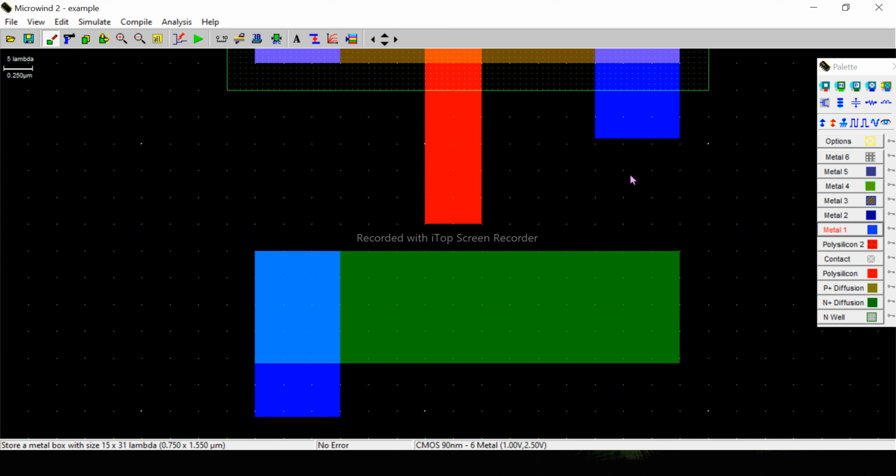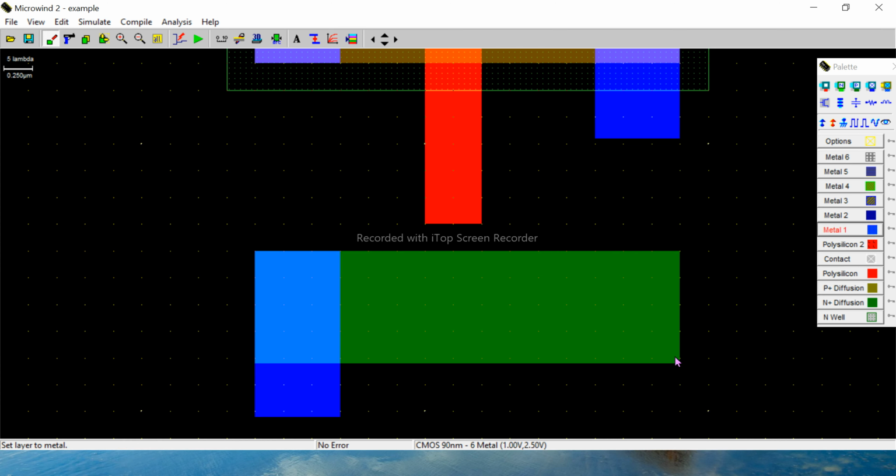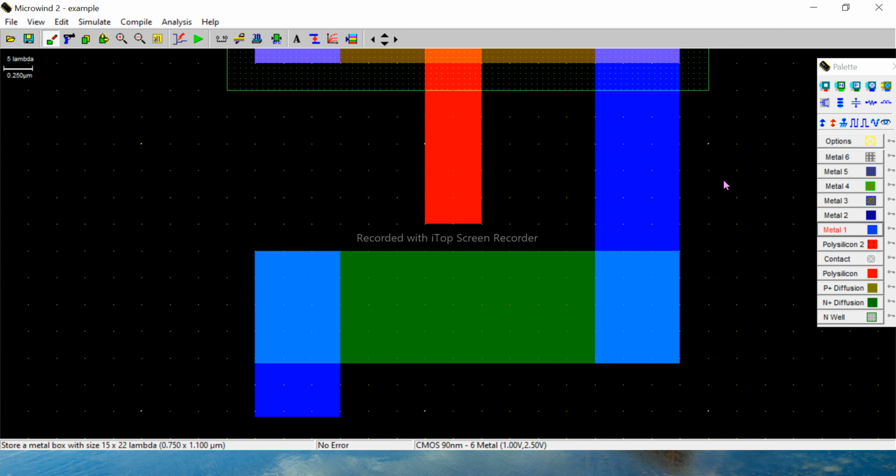Because here I need to make the short, both the drains are to be connected. So I'm taking the NMOS drain over here. I'll draw this drain in the upward direction, because we know that the output of this inverter occurs from the shorted drain terminals, and directly I'm connecting both of these. Why? Because I need to obtain an output over here, and we have now completed source and drain.